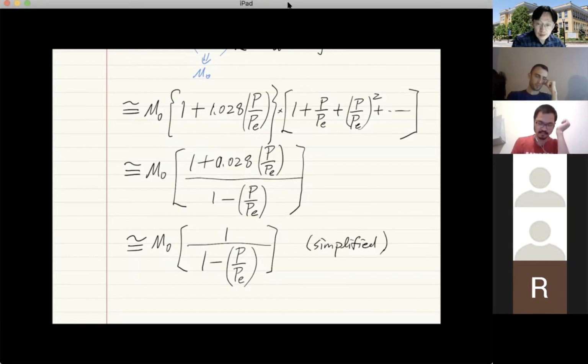Nonetheless, from this expression, it does indicate the amplification of moment due to the application of axial force. So when you see the expression of a maximum as a function of axial force, you know that the bending moment will be amplified by axial force. Right?